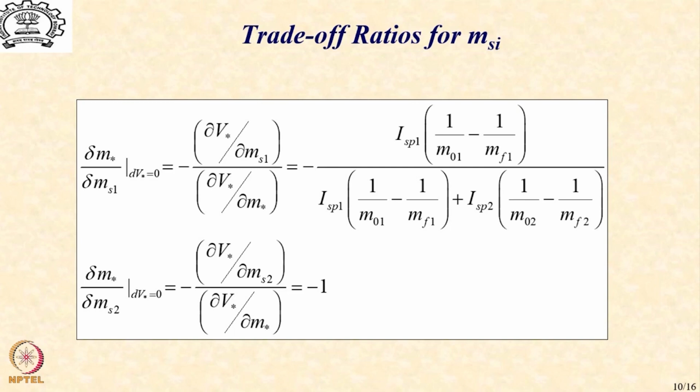it immediately allows me to add 1 kg in the payload mass, and that tells you that this is the best possible efficiency that one can get. That you are trading off 1 kg of structural mass with 1 kg of payload mass. Conversely, if you want to increase payload mass by 1 kg, you must reduce 1 kg of structure from the second stage. Of course, this number is going to be less than 1 in the case of ms1. So obviously the efficiency is lower.